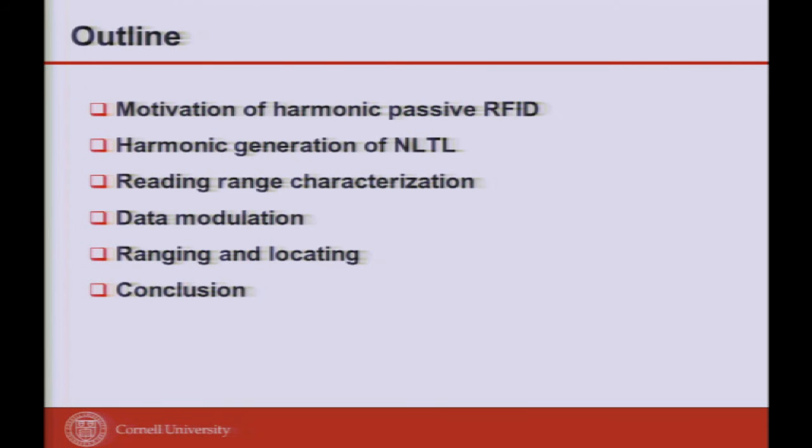So I'll tell you about the motivations of a different way of doing passive RFID, called harmonic RFID. This is not really new; it has been going on for quite a while, from the radar days. But we developed more theory, implementation and experiment for this concept. I'll tell you about harmonic generation using a specific way called the nonlinear transmission line.